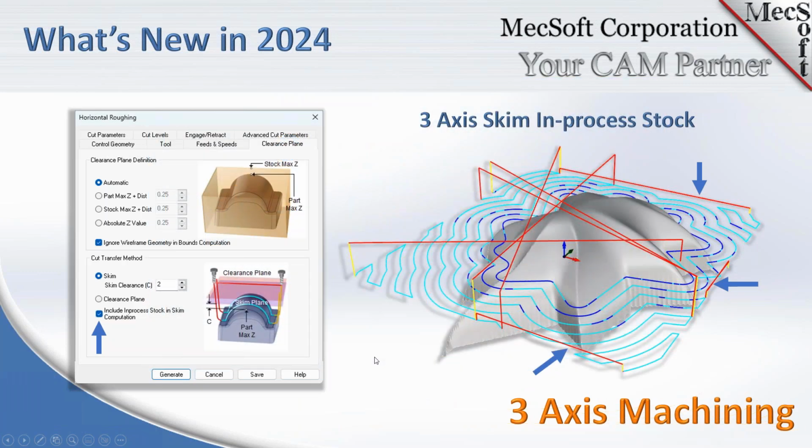Now, for 3-axis enhancements, this is a pretty good enhancement here. If you look at where the arrows are, we're looking at horizontal roughing, and we're looking at the clearance plane tab in the cut transfer method. So the clearance plane definition in this example is set to automatic. And then below that, we have the cut transfer method set to Skim, but we've also added a checkbox here to include the in-process stock in the calculation of the Skim clearance.